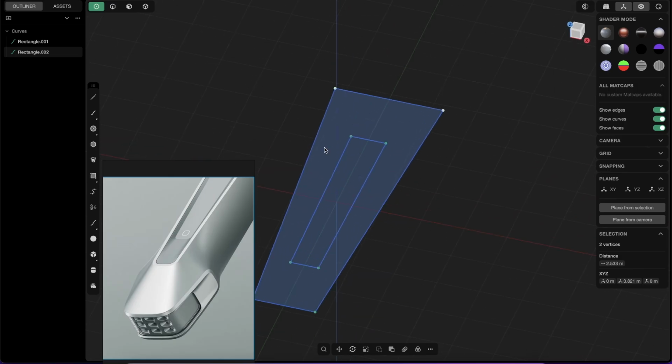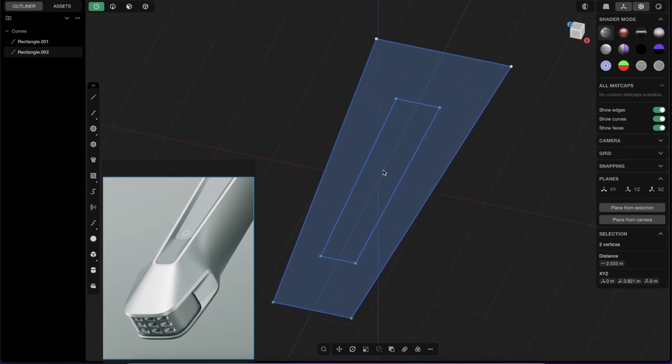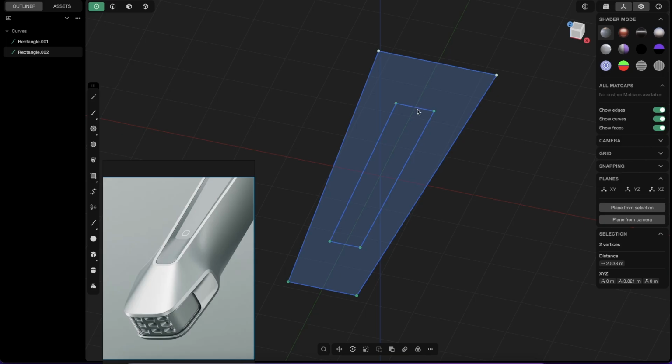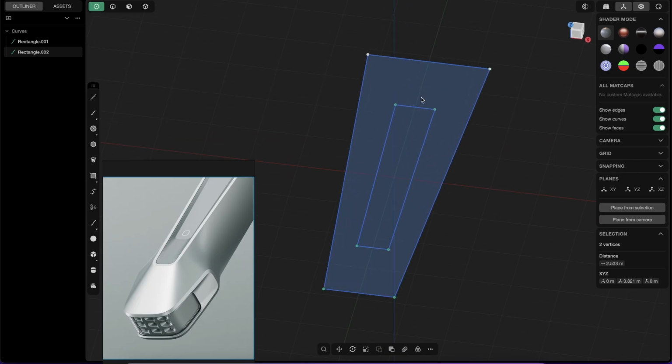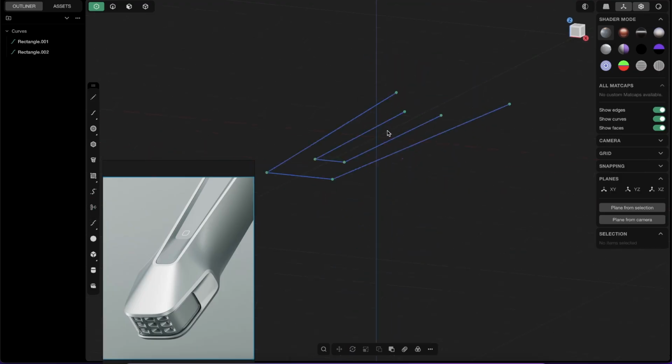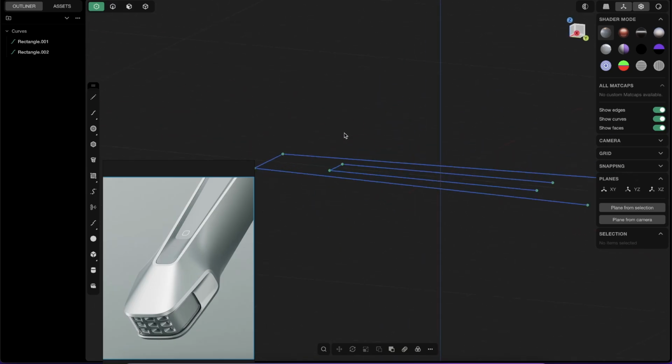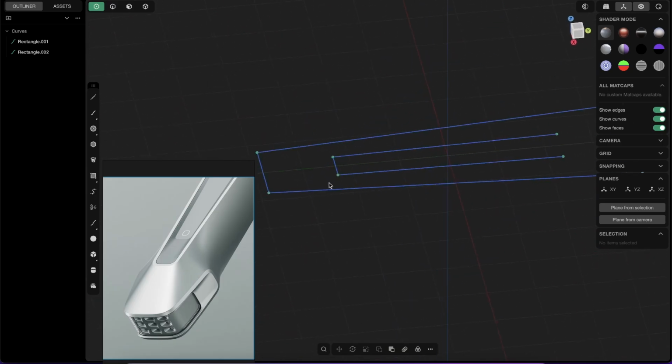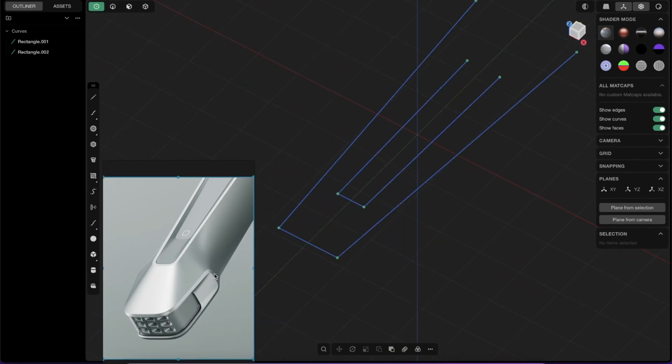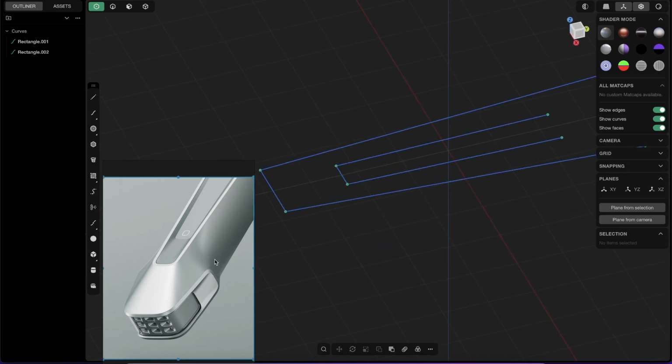And now I don't want that everything is blue here. It's just a little bit confusing. And anyway, we don't need those end lines. So I will just go here to the trim command, to the scissor, or just press T and just delete this one and this one, right click to confirm. So we have this nice situation. Also, you see that here this front piece is not going towards the end. So it stops somewhere here, right?